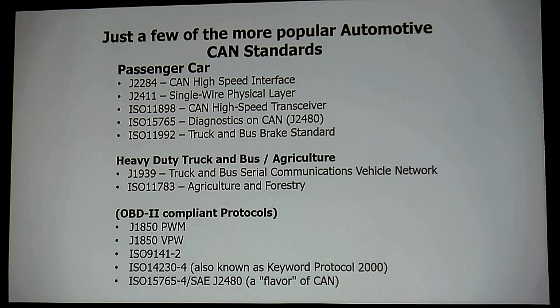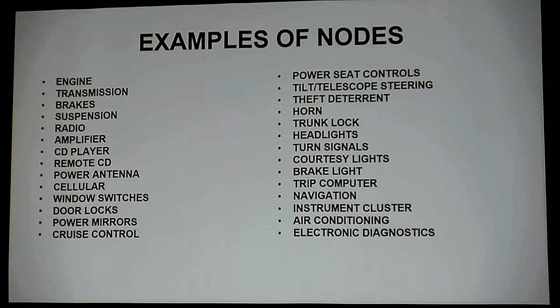We're going to talk about the bit timing edges, but these bit timing edges start to become really critical in order to process messaging. If I have really long buses, you can't run them as fast. You have to be slower when you do an arbitration-style bus, and we're going to talk about what an arbitration-style bus is. So here we would have some examples: engine, transmission, brakes, suspension. Wouldn't you think that those things would need to be on a faster bus?